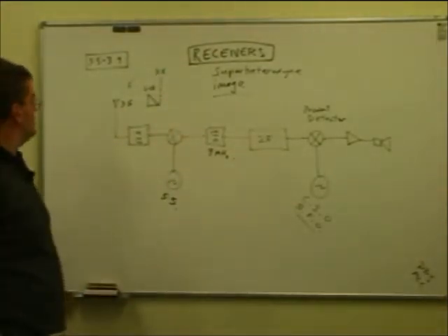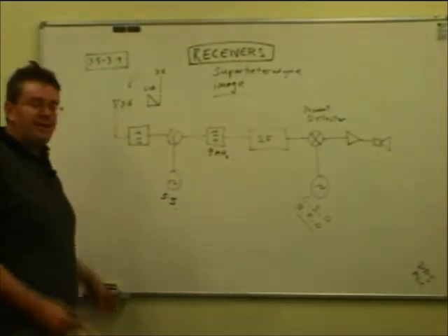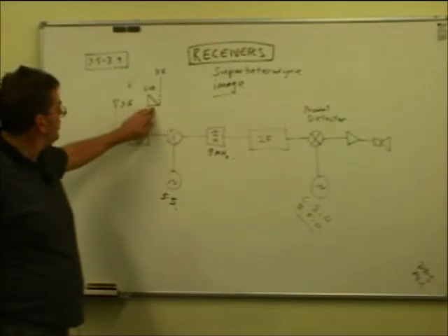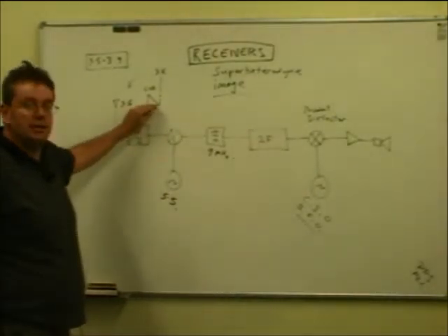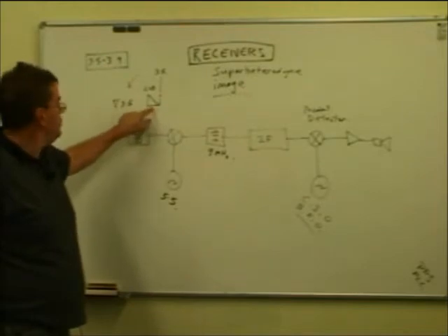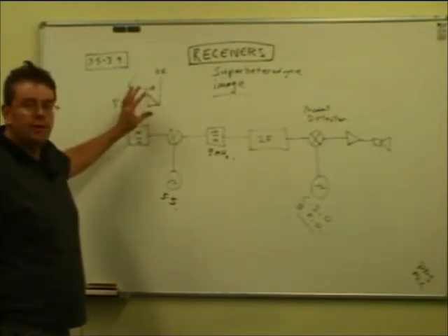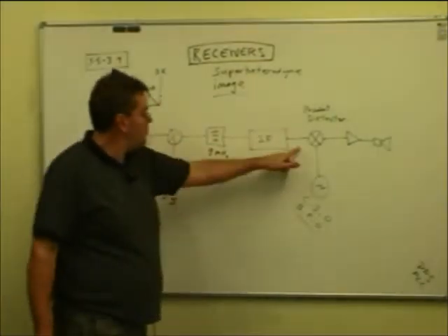3.5 no longer exists. We've only got this bunch of frequencies just below the carrier, which is our sound from our microphone, if you like, that's been shifted up in frequency, and it's just below. Remember, when it's silent, no one's speaking, there's no energy there. As you talk, if you whistle a single note, there will just be one signal there, a number of frequencies in our voice, there'll be a whole bunch of them. And that's what's coming out at this point here.